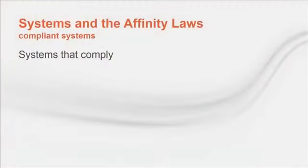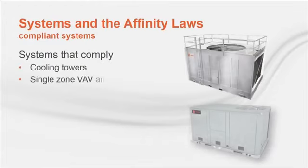However, the device is at the mercy of the system, and its operation must comply with the system requirements. What if the system does not follow the same pressure and flow relationships as generated by one of these devices? First, let's examine a common example of a system that has the same operating characteristics as a dynamic compression device, and then one that does not. The two best HVAC-related examples of systems that comply with affinity laws are cooling towers and single-zone VAV systems. They may be the only two that comply well.